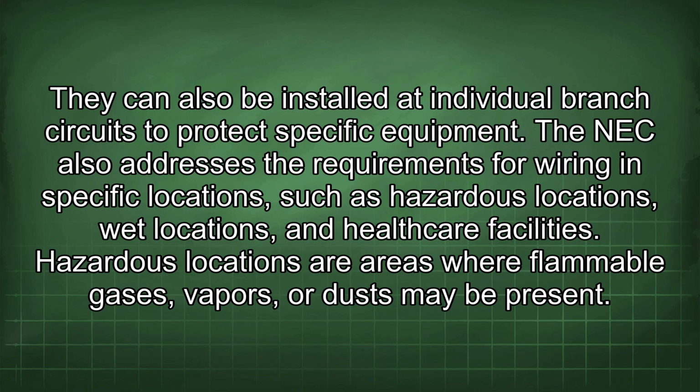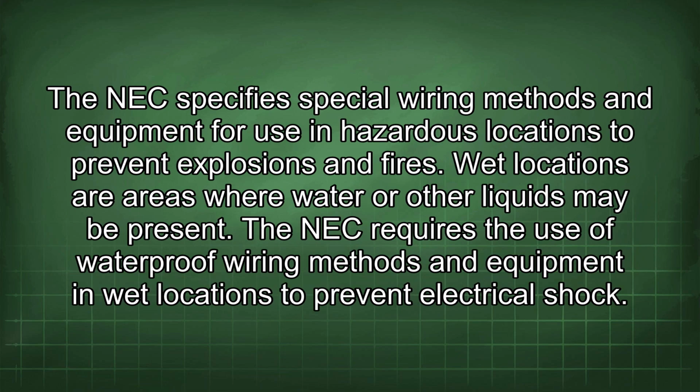The NEC also addresses the requirements for wiring in specific locations, such as hazardous locations, wet locations, and healthcare facilities. Hazardous locations are areas where flammable gases, vapors, or dust may be present. The NEC specifies special wiring methods and equipment for use in hazardous locations to prevent explosions and fires. Wet locations are areas where water or other liquids may be present. The NEC requires the use of waterproof wiring methods and equipment in wet locations to prevent electrical shock.